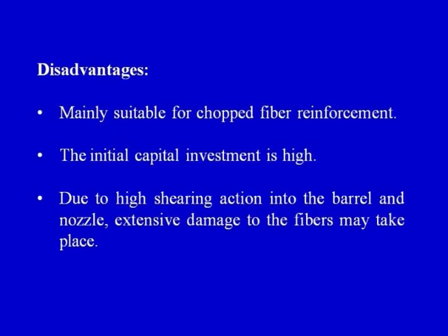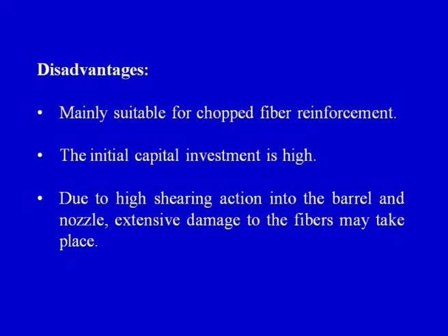The initial capital investment is high, because the cost of the mold is extremely high, which I have already mentioned, and the cost of the setup is also high as compared to the hand layup process or the spray layup process, and also in comparison to the compression molding process. So the initial cost of the machine is high, and the cost of the mold is also very high. Due to high shearing action in the barrel and nozzle, extensive damage to the fibers may take place.